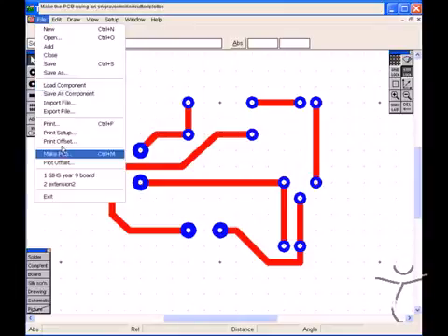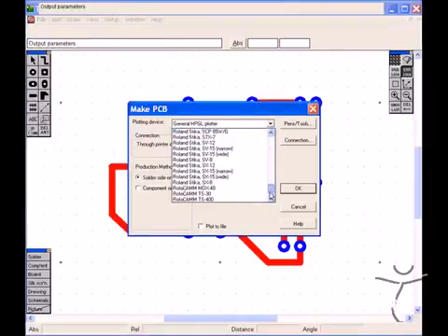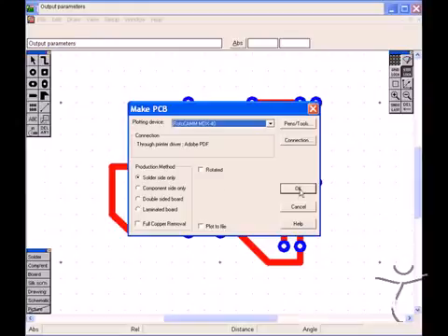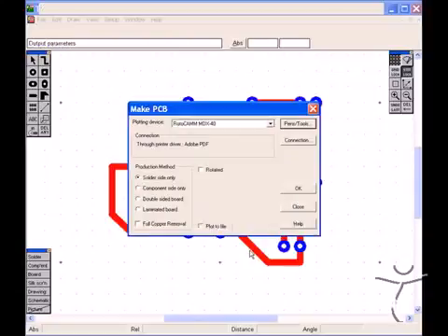If we go to make PCB through, say, the MDX 40, we define the engraving option. Be careful, this is rather fast for copper. And if we tick this drill number 1 to be 0.8, that will find the 0.8 millimeter holes and drill them.